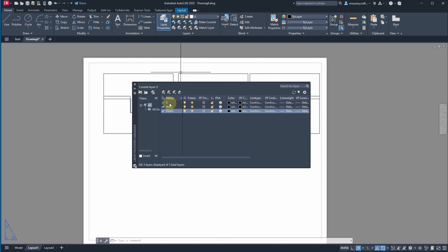Or even just in your normal project. And I've seen people who turned off one layer and all their doors disappeared, because they built on whatever that initial layer was, and those just weird things happen. So always build on your 0 layer, and then you want to move things to other layers.